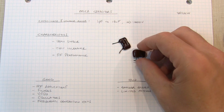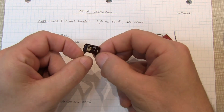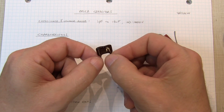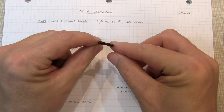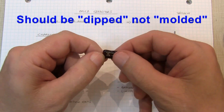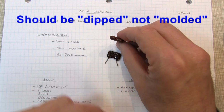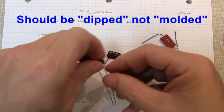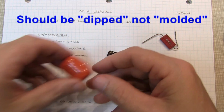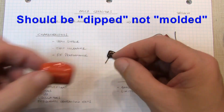Now, you might say these look an awful lot like those molded film caps. Now, the way you can generally tell the mica caps apart is that they're a bit lumpy, if you will. If you take a look at this package, it's kind of bulged at the ends, or maybe almost a little bit dog bone shaped, if you can think about it that way in terms of the way the package is, compared to the film caps, which are generally a bit more smooth and I would say cylindrical, or just don't have the lumpiness, especially associated at the ends.